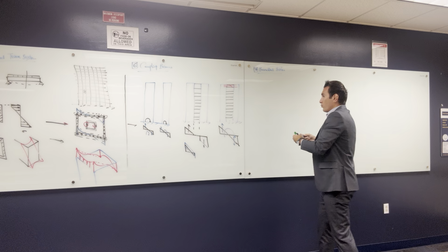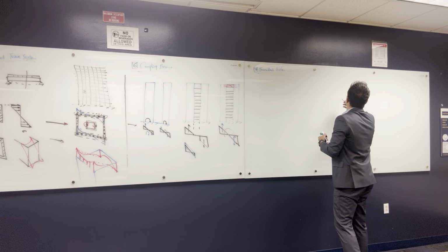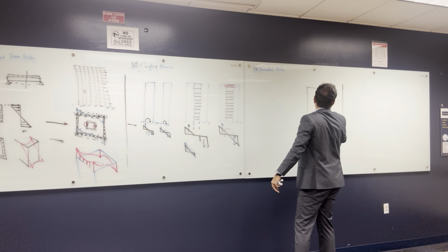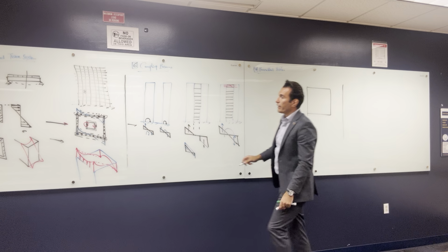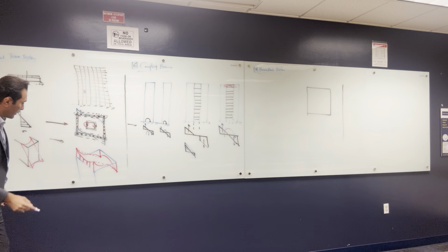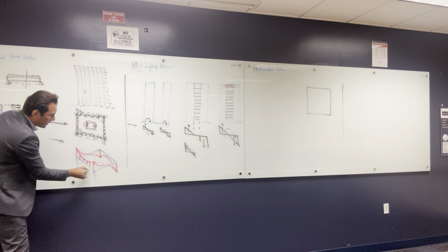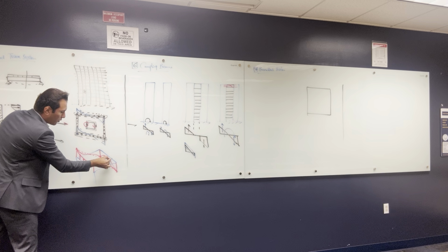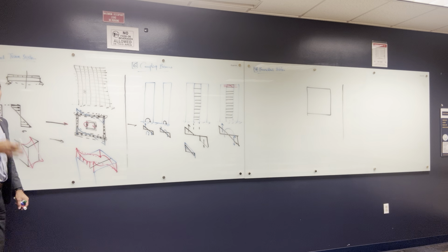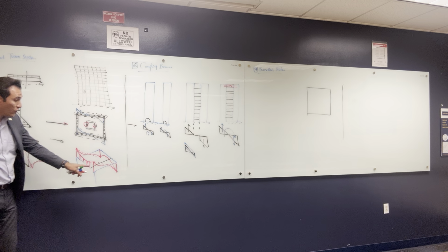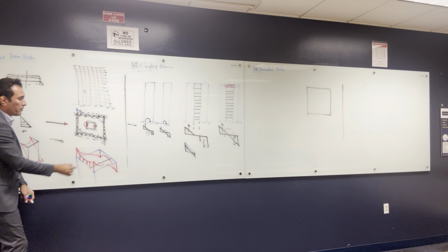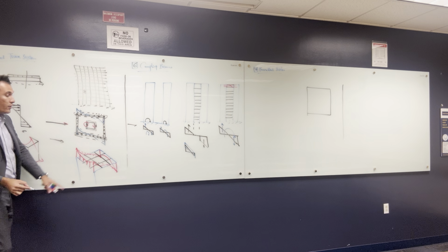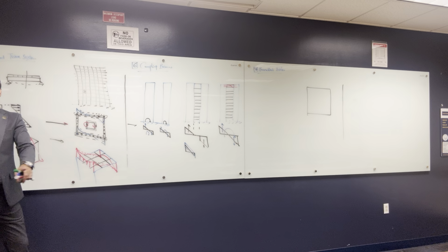Okay, so let's say our building is like this, a rectangle, and the shear lag, what happens here, for example, it goes all the way down. But what if we make another shear wall here? I mean by shear wall, a perforated shear wall, like a bunch of columns very close to each other inside the building connected with very strong beams, and we make it another time. And the same thing that way and that way. So it becomes a bundle of tubes.